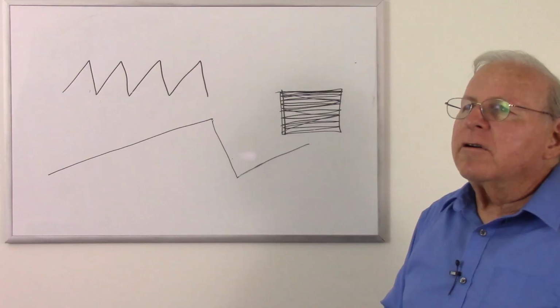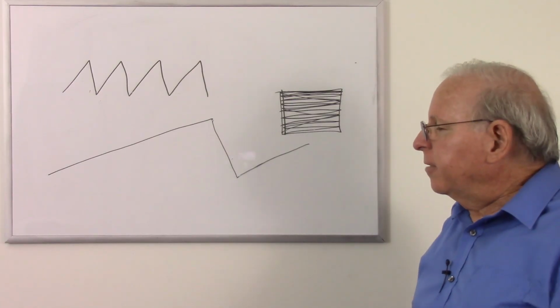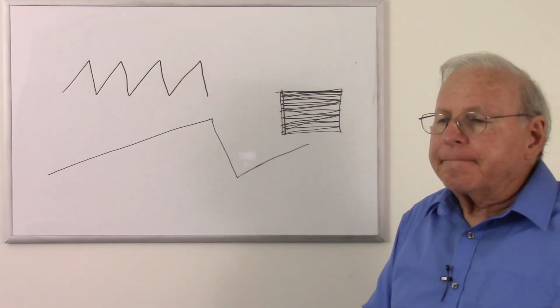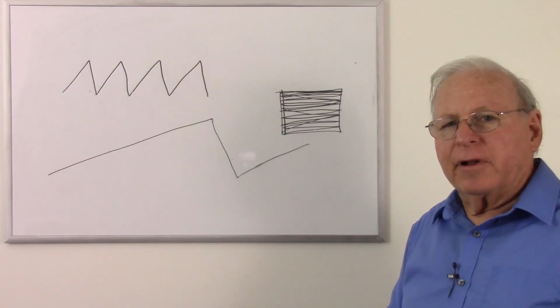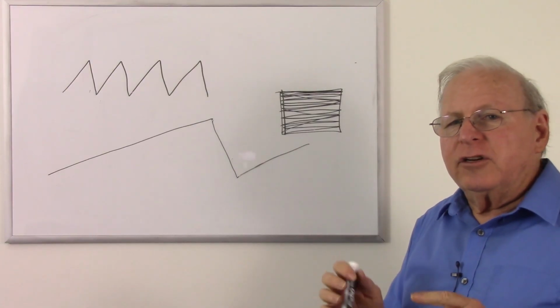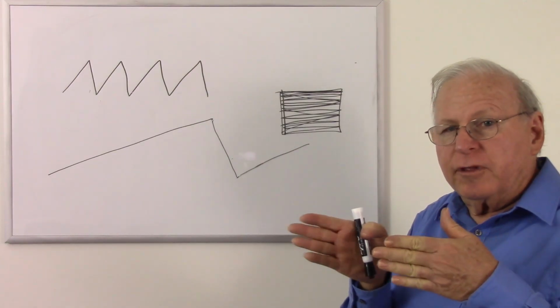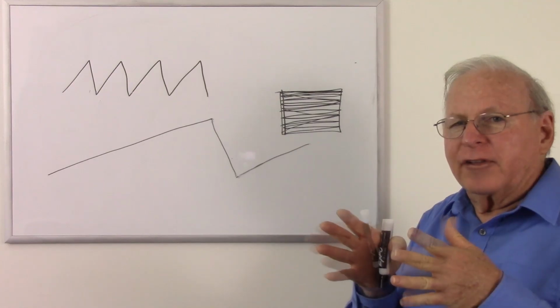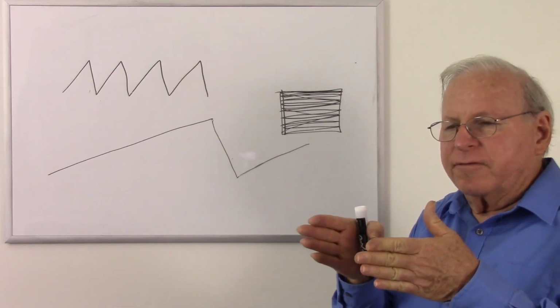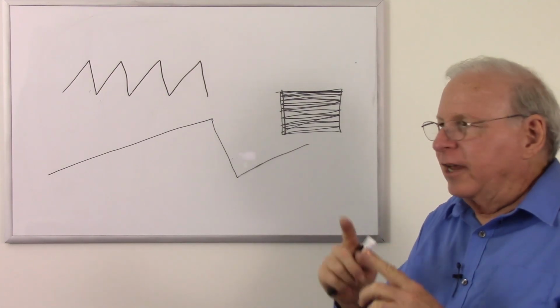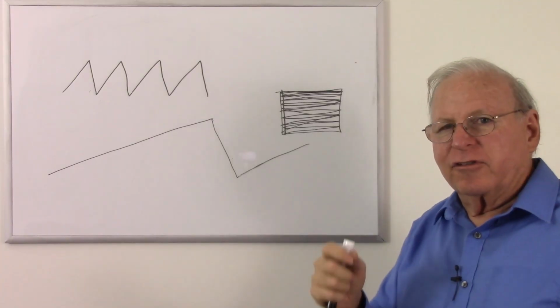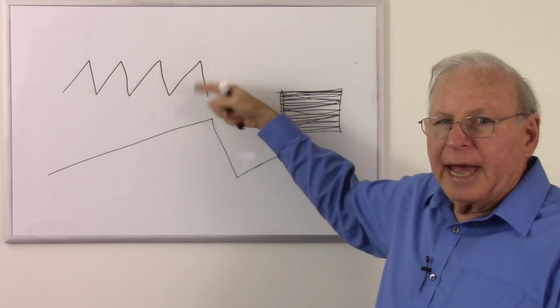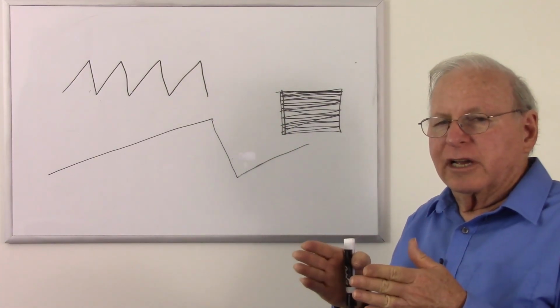Now, I don't know if he ever used electrostatic plates to do this, but some systems, for example, analog oscilloscopes, tend to use electrostatic plates to move the beam, but it's the same concept. Instead of magnetic fields, we use electric fields, and those are built into the CRTs, and we still have to have the same oscillators and such, but instead of sending current to magnets, we send voltage to electrostatic plates.